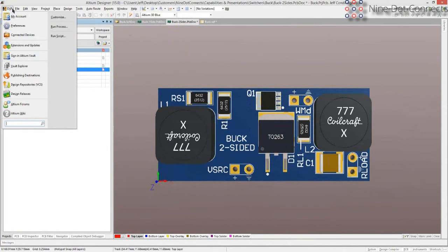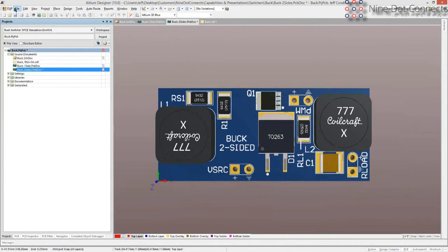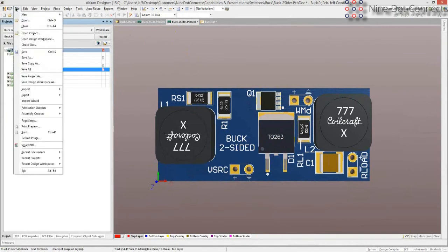Okay, we have another question. Does diode reverse recovery in the neighborhood of 35 nanoseconds create a current shoot-through? Sometimes, in certain circumstances, it can. Again, they're fairly rare.